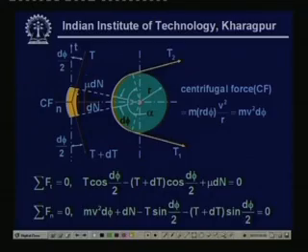Now, you can see that because this belt has got a movement in this way, just at the impending condition, you understand the impending condition means the point where the belt and the pulley are just having a relative motion. Under that situation the forces acting onto the belt segment are shown in this particular figure.